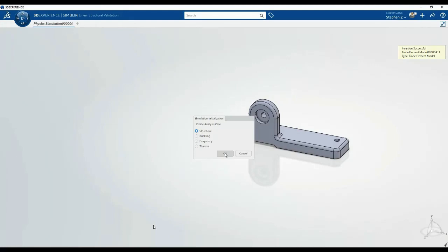The one problem with that, which is why I want to point this out early, is that if you have multiple roles, right? If you have your structural designer role, so your simulation standard equivalent, and then you go ahead and open up the simulation you created in the more advanced role, say simulation premium or structural mechanics engineer, and you go ahead and save over that data, it's actually going to convert that data into something that only structural mechanics engineer can use. So if you have one kind of designer who's doing the basic simulation stuff like this, and then you have one analyst who's doing the higher level stuff, if they save over that data once it's open in structural mechanics engineer, the structural designer engineer is not going to be able to open it anymore.